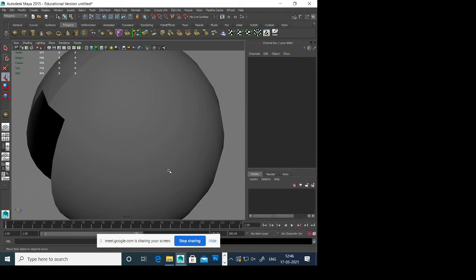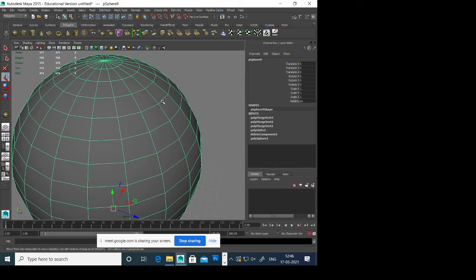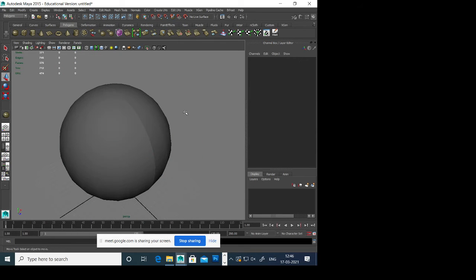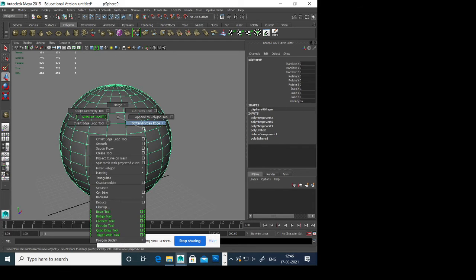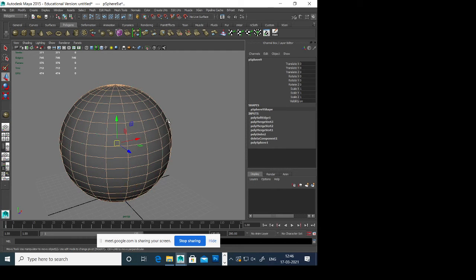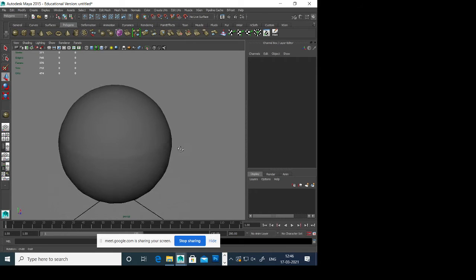So here you don't have the option. But whenever you weld something, you can see this is a hard line. This is basically a hard edge. In Max, you don't have hard edges, I guess? No, you don't. By default everything is smooth. You apply one smooth to everything, everything becomes smooth. So basically this acts as a separation of smoothing groups. Both are the same, but this edge is separating the shading. So I can separate the shading, or to smooth the entire thing, shift, right click, down, soft edges, done. Similarly, if I select something, shift and hard edges, it will create that shading.